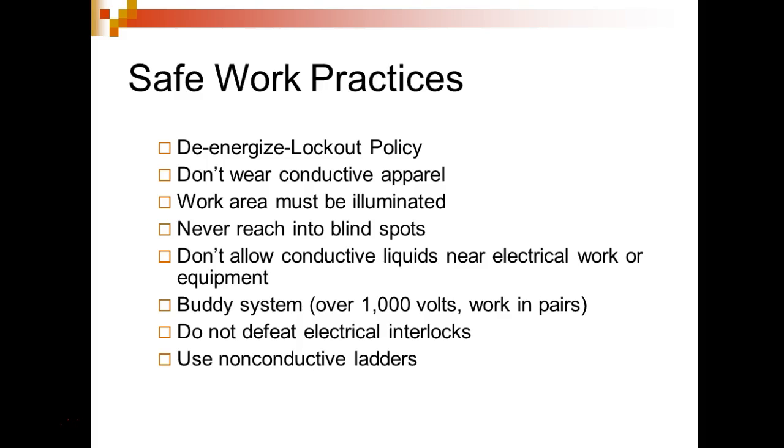De-energized lockout policy. So we're going to do that in this class, even though we're below the 50 volt standard. We've got plenty of locks. We've got plenty of tags. So when you're troubleshooting, you're going to be able to use the meters, but when it comes time to rewire something or replace something, what are you going to do? You're going to lock and tag all power sources. 70E only determines the energy, but lockout tagout means to lock and tag all sources of power.